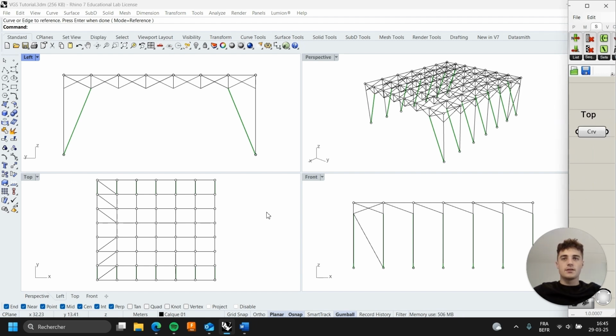Then this truss also needs to be braced in the x direction. So let's examine the xy plane. The truss will resist the x direction thanks to diagonals there. And we notice that one cell doesn't have any diagonals. It's because that would lead to hyperstaticity. So all of this forms a stabilization span essential to the stability of the whole system.